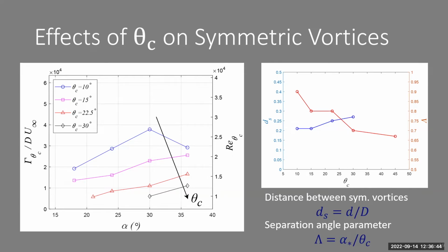These are all on a smooth cone, right? What's the roughness, and how did you measure it? How smooth are these? So the cones are sanded, polished, and coated with paint. However, since we're dealing with low speed flows, the order of that surface roughness compared with the order of the boundary layer thickness is negligible. So we didn't actually provide measurements for surface roughness.